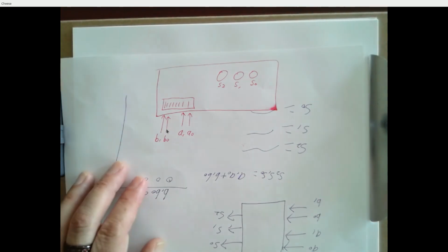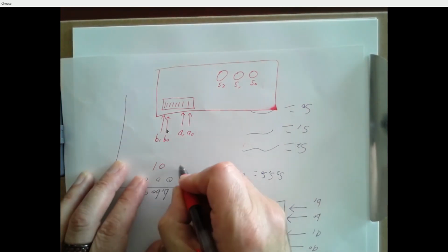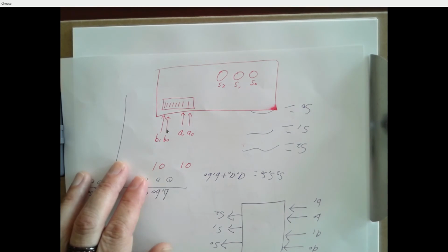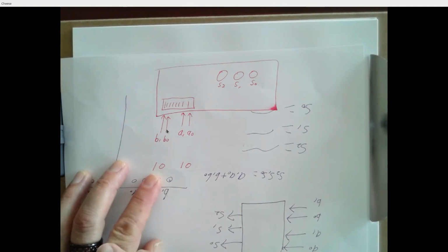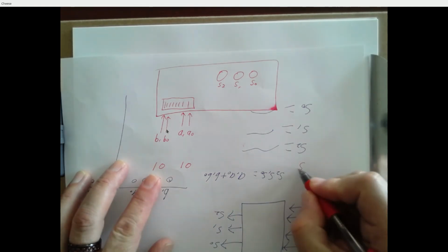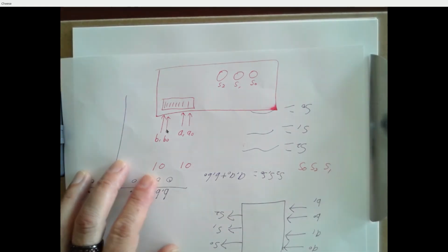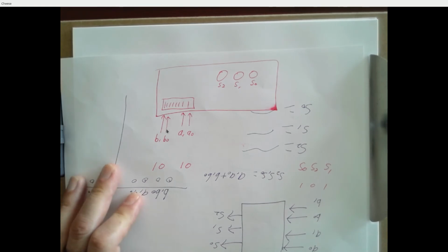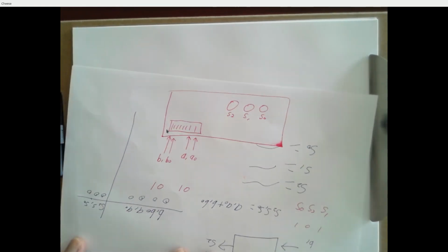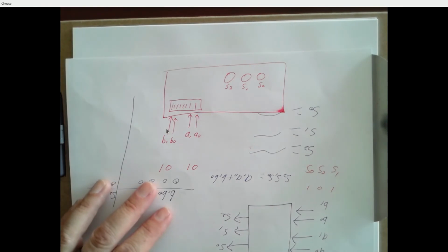If you flip these around and then you do 1, 0, 1, 0, you've got to mentally in your head say, okay, this is B0 and B1, so this is the number 1 and this is the number 2. That should add up to 3. And if you set up your LEDs to be this, then you got to mentally say, okay, so a 3, that should be on and off and on, right? And you can spend a lot of time trying to figure out if your circuit works correctly or not. And worse, your circuit might be working correctly and you're misinterpreting what it's doing, and you get frustrated and you rip your wires out and start over, right? So it's really easy if you think about it ahead of time.